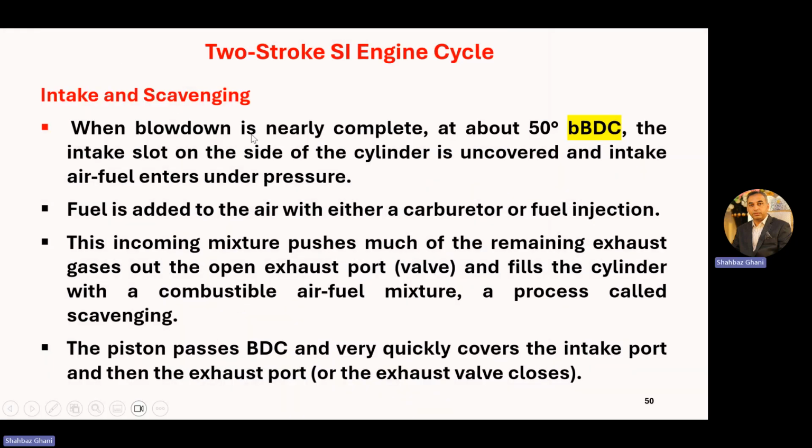Intake and scavenging. When blowdown is nearly completed at about 50 degrees before BDC, the intake slot on the side of the cylinder is uncovered and the intake air fuel mixture enters under pressure. Fuel is added to the air with either a carburetor or fuel injector. This incoming mixture pushes much of the remaining exhaust gases out of the exhaust port or valves and fills the cylinder with the combustible air fuel mixture, a process called scavenging. So the removal of exhaust gases with the help of air fuel mixture is called scavenging.